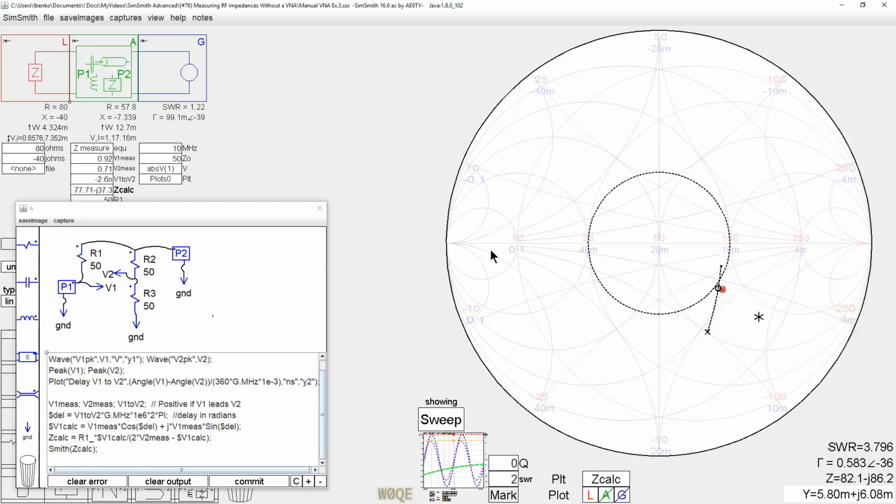I held them there. I captured this waveform on the scope and then stopped the refresh. So it's nice to have a scope that you can do a single trace and then stop, in terms of holding stuff, but you don't get any more accuracy. If you're careful enough and hold it there with a regular conventional scope that has no storage, you can make the same measurements just as accurately as this. These numbers are pretty close together.